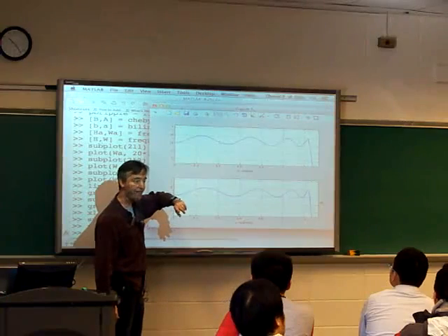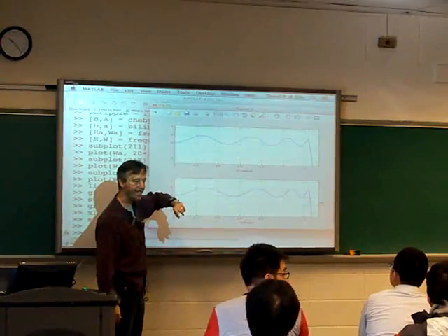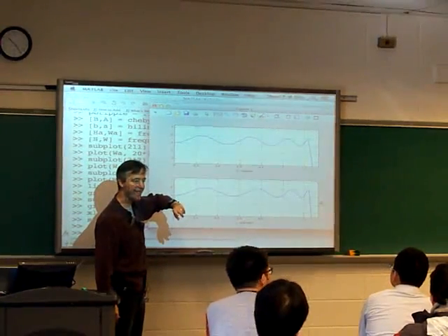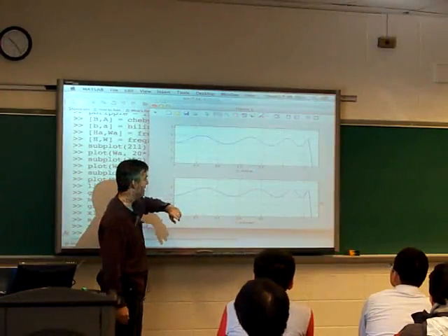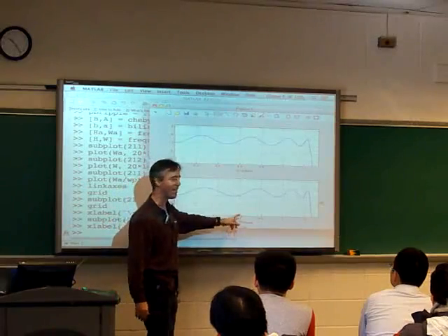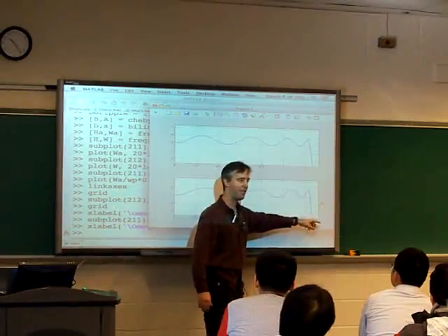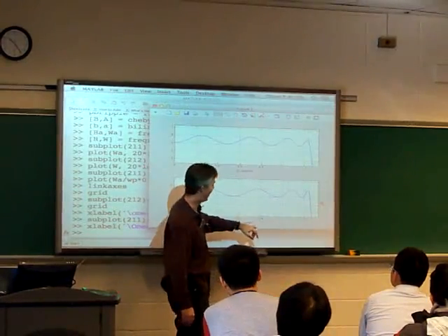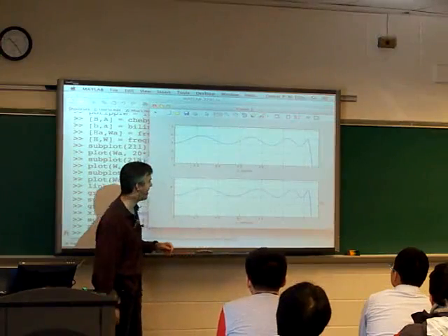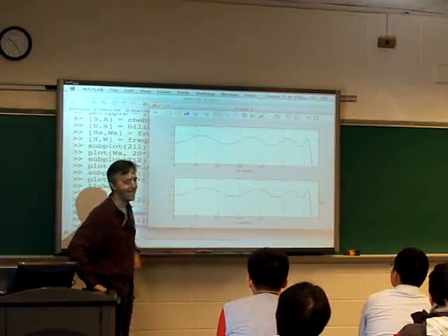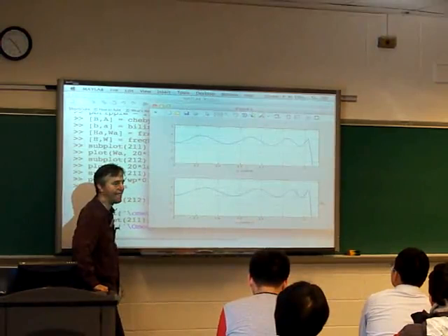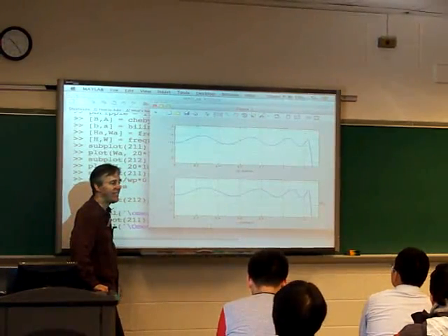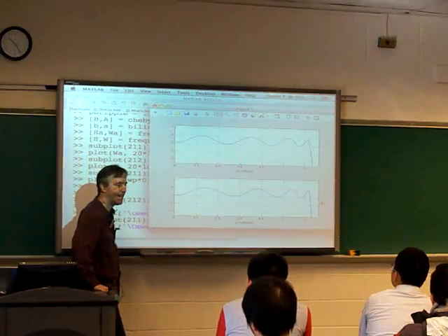Yeah. The discrete frequency in the x-axis, is that normalized to pi, or it's not? No, this isn't. I didn't normalize it. So you saw that it went up to 3.1. Normally I plot it normalized by pi. I didn't. So it's actual radians per sample. The response of that would be like from 3.14, pi, to 2 pi would be 0, and then from 2 pi onwards it repeats the same way.